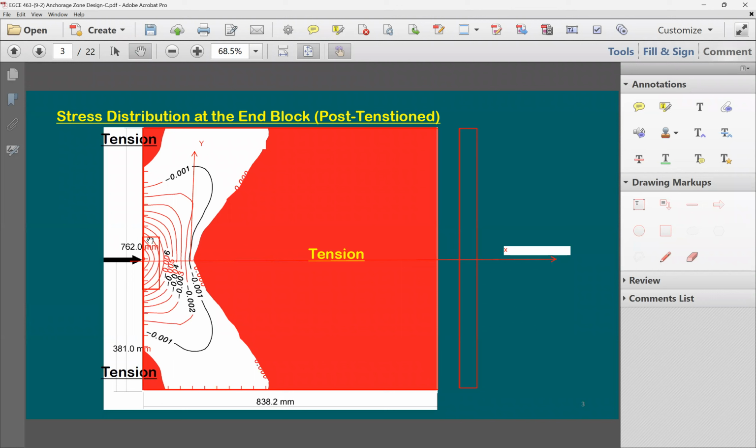And because the stress here has an angle, as if it's directed this way, you have a small component that is going to see some tensile stresses, top and bottom. Of course, we have symmetry about the x-axis. Whatever is happening on the top is the same as what happens on the bottom. The big tension force is going to be right here in the middle.